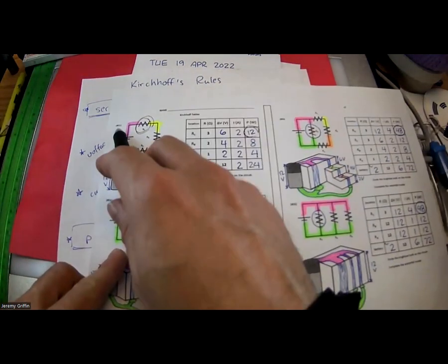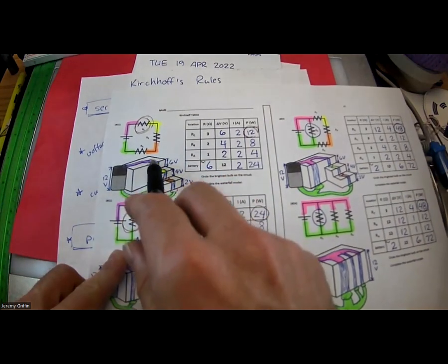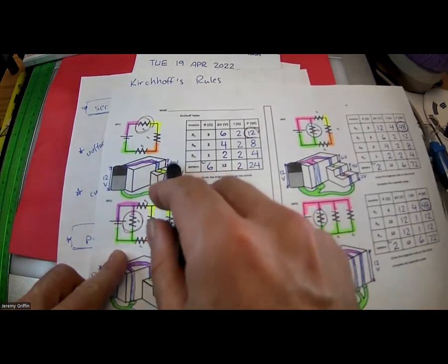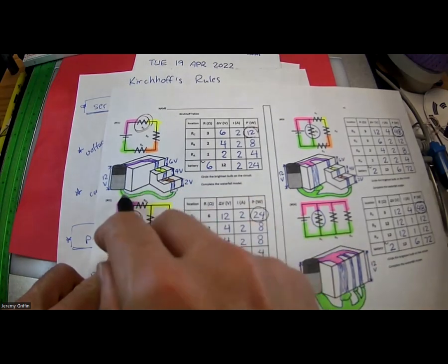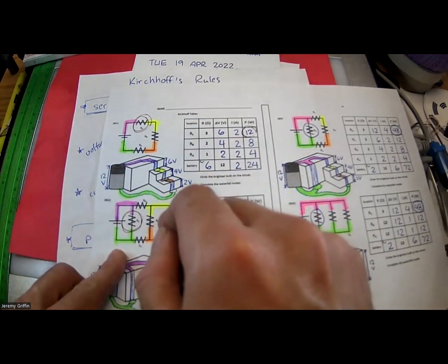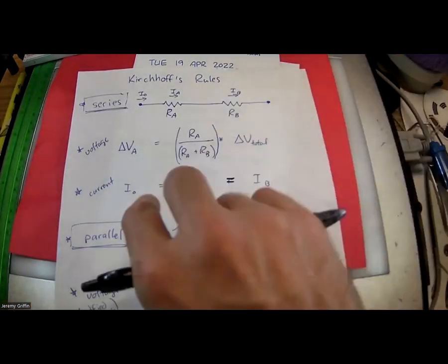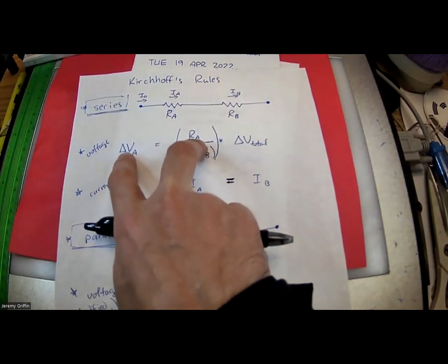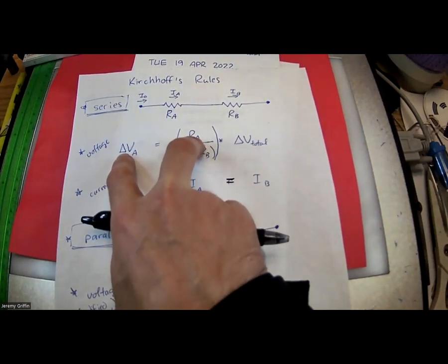All right, here's straight series setup. Right, drops a little bit. But these waterfalls are all different heights. Right, now they have to add up to the battery, but they're all different heights themselves. Right, and in fact, there's a greater voltage drop for a greater resistor, right? The greater the resistor, the more the voltage drop, right?